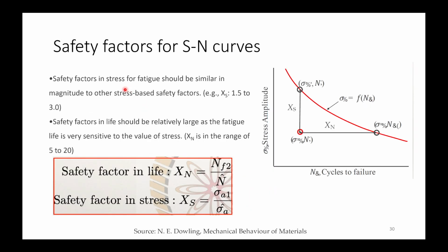Now there are also safety factors that are required for SN curves. We cannot directly take the number of cycles from the SN curve; we need to consider some safety factors. Now safety factors in stress, or this can be either in cycles.